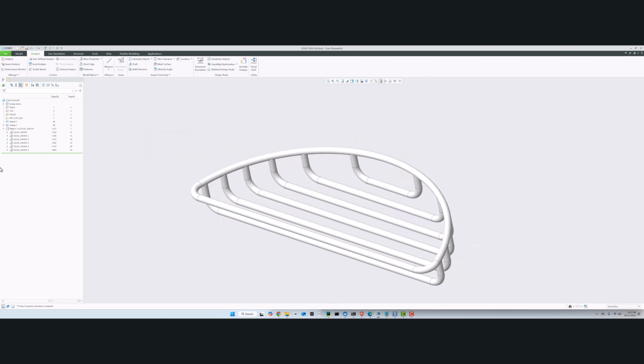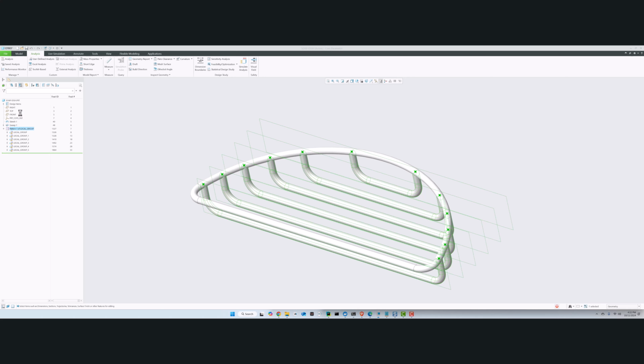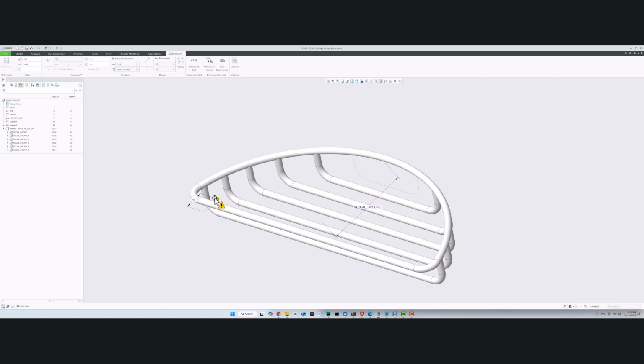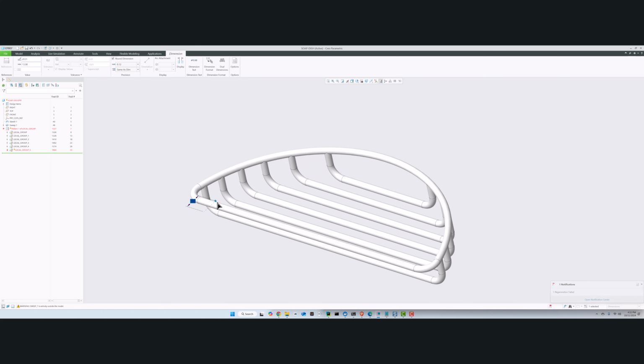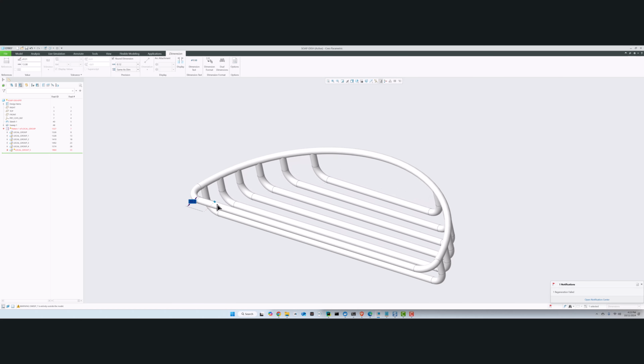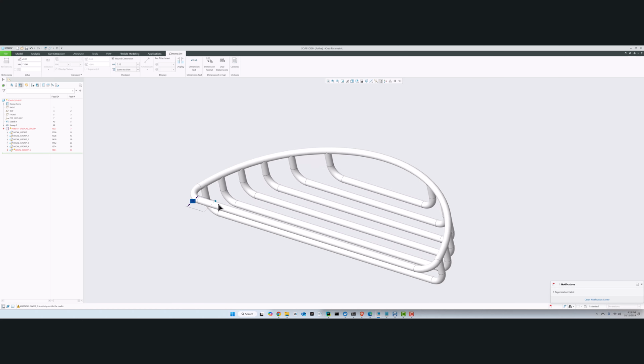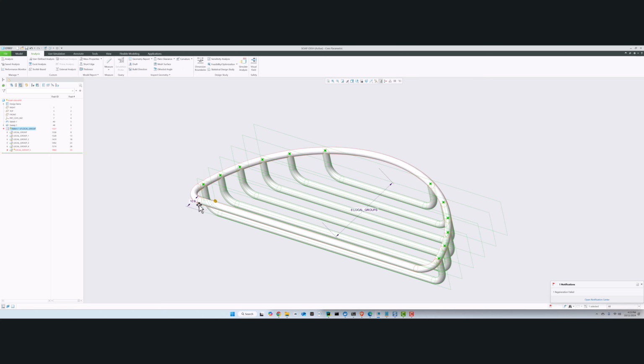But let's push it a little bit further. Let's say someone else comes in and says, you know what, I want this spacing to be more like, let's change this from 12 to 13. Is the model going to blow up? No, things are just going to change. In fact, I can sort of drag this as we go, and Creo will do what it needs to. I could write a relation to control these, but as you can see, these sketches are adapting just as they should be, giving me the ability to control these things with real numbers.